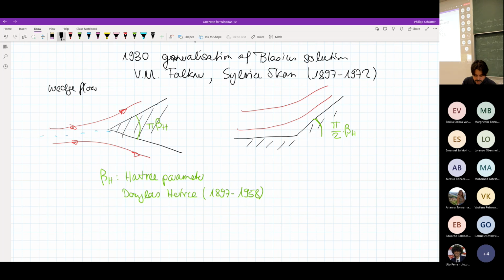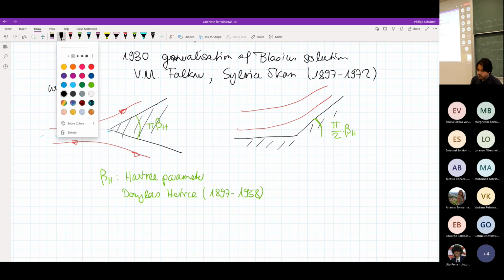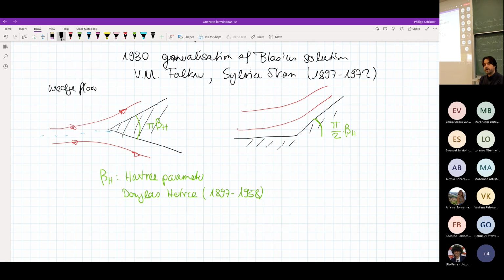Okay. So now how did they actually come up with this Falkner-Skan solution, or what is the difference to Blasius? Well, if you recall Blasius, the flat plate when the angle would be zero, there we defined our eta, our similarity variable, as a constant times y times x to the minus 1/2. That's the result that we got at the end for our similarity variable.